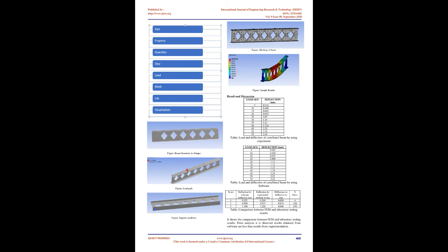Terminology in castellated beam. Before going to analysis of castellated beam it is important to understand few basic terminologies used in the geometry of castellated beam. These terms are illustrated in the following figure 3.1, where D0 equals depth of opening provided. D equals overall depth of the opening. S equals center to center spacing between the two openings. E equals clear distance between two openings. B equals width of flange of I-beam. TF equals thickness of flange of I-beam. TW equals thickness of web of I-beam.